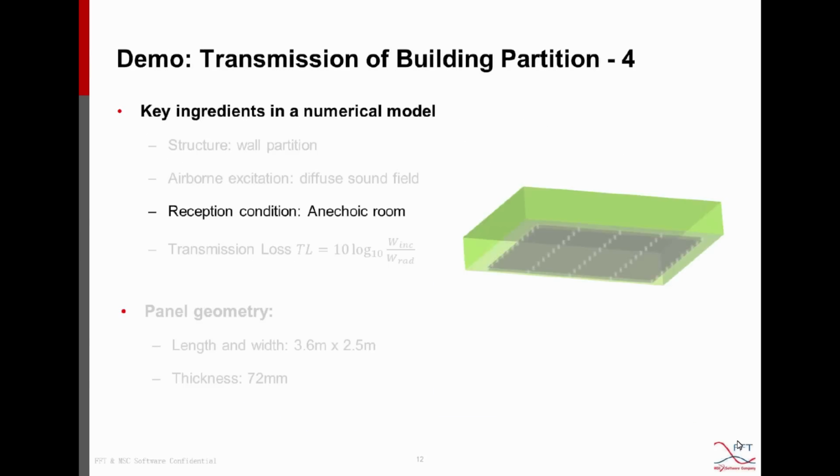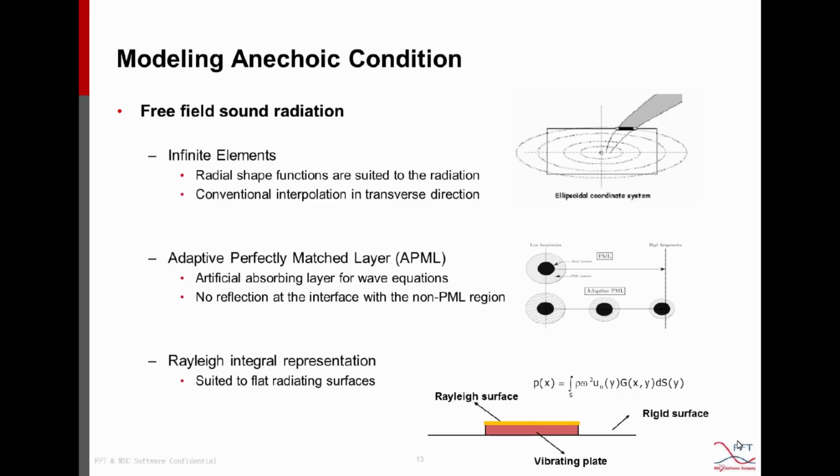The last component in this numerical model is the reception condition. In this case, we want to define an anechoic room. In Actran, there are several ways to model the anechoic room, or in other words, to model a free field sound radiation. There are infinite elements.